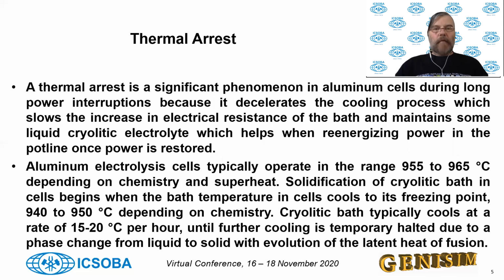When we are modeling the cooling down, and when we are observing a cooling down physically, an important physics that's occurring is called thermal arrest. It is simply when you have a phase change between liquid and solid, the latent heat slows down or stops for some time the cooling rate.